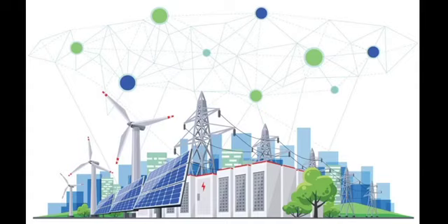Common types of power quality mitigation equipment. Voltage regulators, stabilizers. These devices help maintain a steady voltage output by compensating for voltage fluctuations, ensuring that connected equipment receives a consistent voltage level. Uninterruptible power supplies. UPS systems provide backup power during outages, ensuring continuous power supply to critical equipment and preventing voltage disruptions. Surge protectors. Surge protectors, or surge suppressors, are used to limit the voltage spikes caused by lightning or sudden voltage changes, safeguarding sensitive equipment.